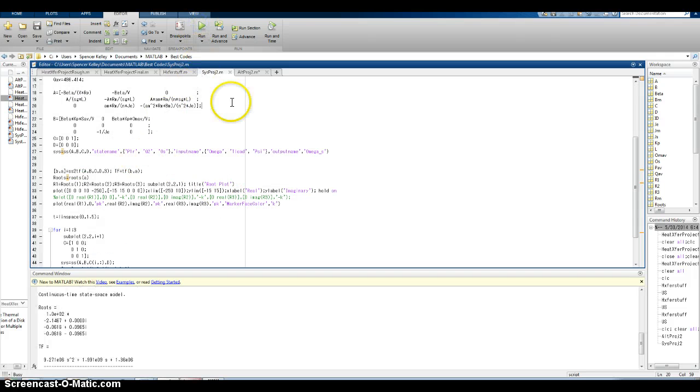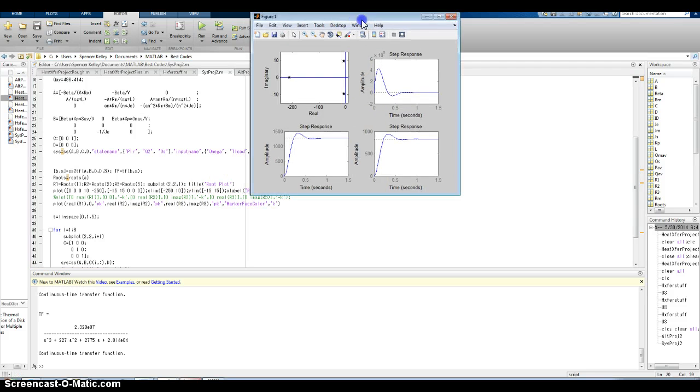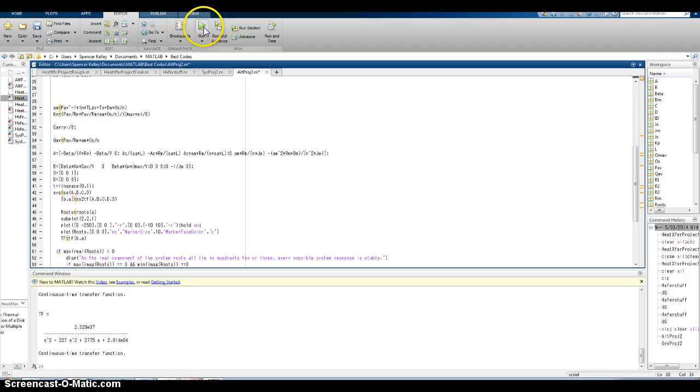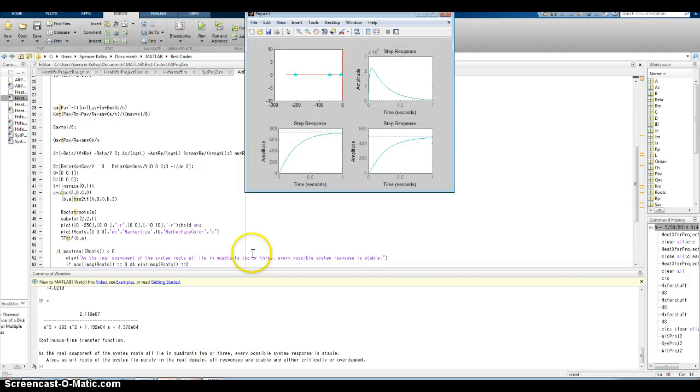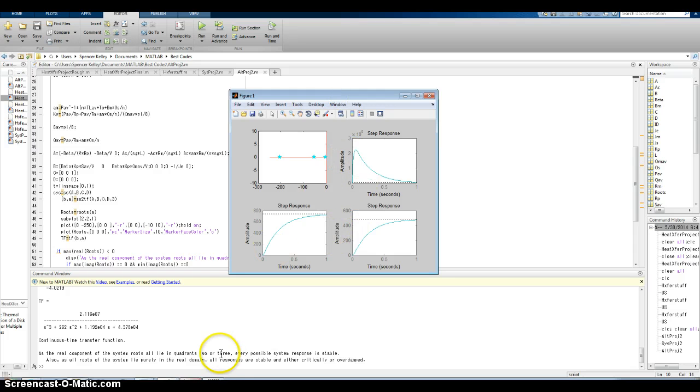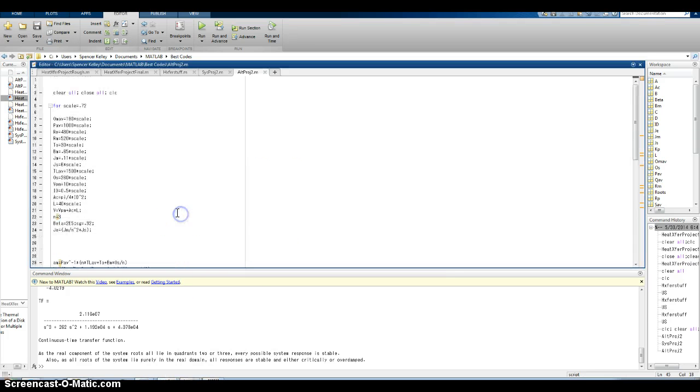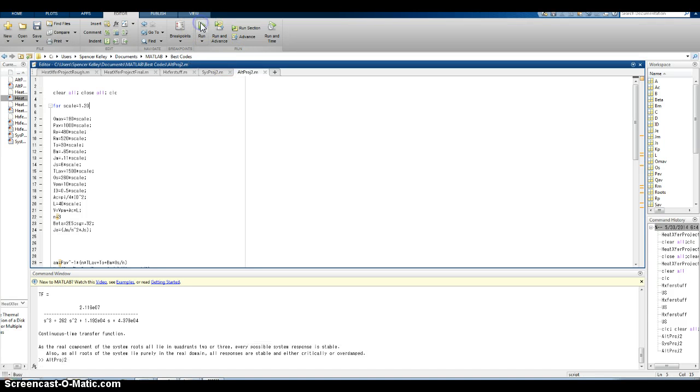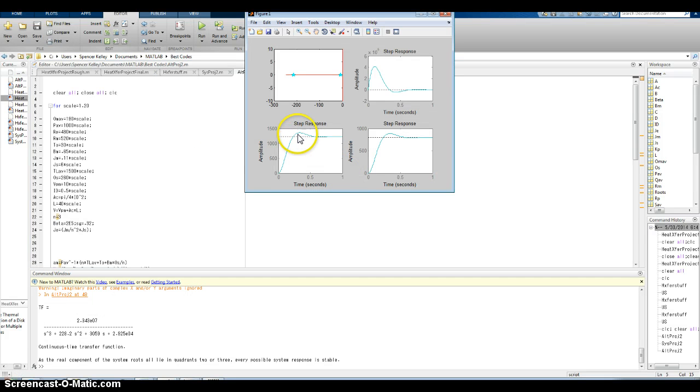So as these codes run, we get not only the responses of the system, and actually both codes will give me normally similar responses. Right now I have the scaling of this secondary a bit different. What's interesting is that if you change the scale and it breaches unity, the actual responses of the flow and the spindle speed switch from overdamped to underdamped.